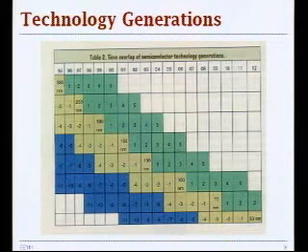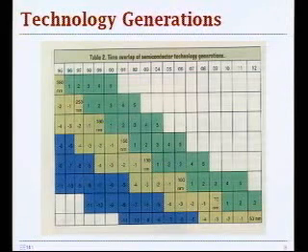And normally, with each generation, when you scale designs, the first time you make it commercially available, you also have changes in microarchitectures that we discussed, like in microprocessors. And then later on, for the couple of technology generations looking forward, you have just the shrinks and compactions until you introduce a new design.